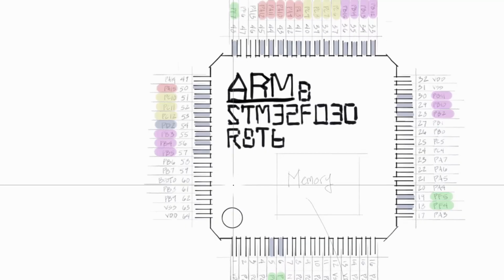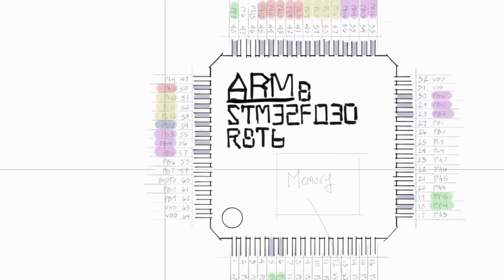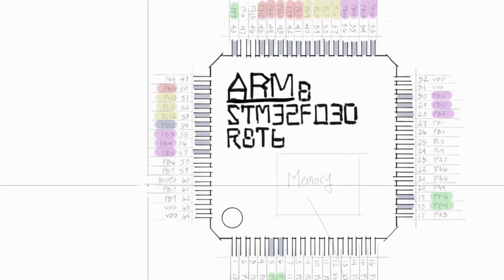And then there's another channel for voltage reference. And this is a voltage reference that is absolutely accurate. It is a band gap voltage reference, which means that it's a constant voltage reference no matter how much variability you're having in your power supply to supply the microcontroller. And this is important because the voltage reference must be very accurate to be able to give you a good reading constantly on an analog to digital conversion.